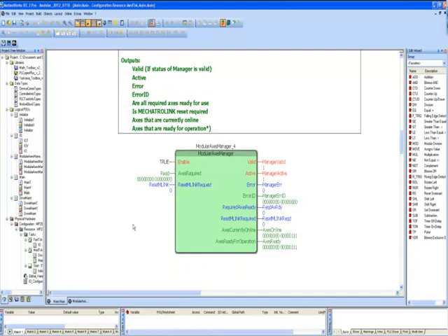Okay, I'd like to show you an example here where one of the axes was basically taken offline. You can see here that axis 1 in this case was taken offline, which means now the controller sees only axes 2 and 3 from this particular output here. Axis currently online, it sees only axes 2 and 3 online, whereas the user had powered on the machine with axes 1, 2, and 3. So let's say the operator now wants to use only axes 2 and 3.